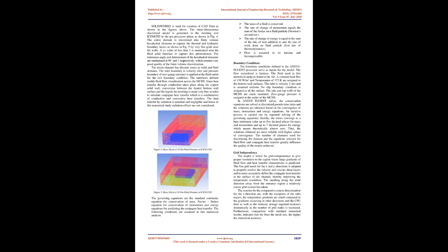Methodology. Microfin heat sinks are designed separately as per the required dimensions using the SolidWorks design tool. The IGES file format of the heat sink file is later imported to the meshing tool to carry out hexahedral meshing by capturing the y-plus value effectively. Once the meshing is done, it is converted to an unstructured mesh file format and imported to the ANSYS Fluent 14.5 solver. In Fluent, all the necessary solid and fluid flow regimes, boundary conditions, and converging residual limits of mass, momentum and energy have been applied satisfactorily. Once the solution is converged, it is imported into CFD-Post to carry out the post-processing activity.